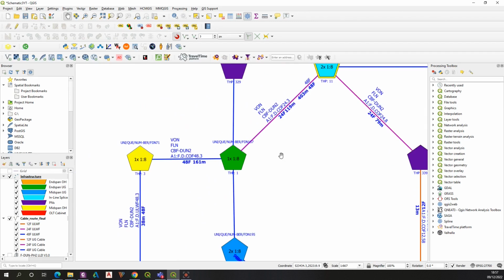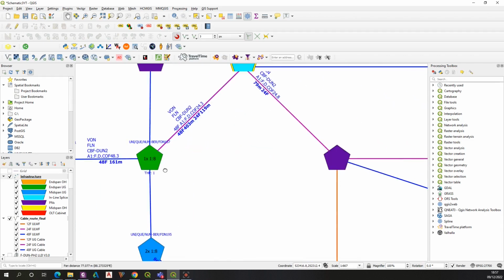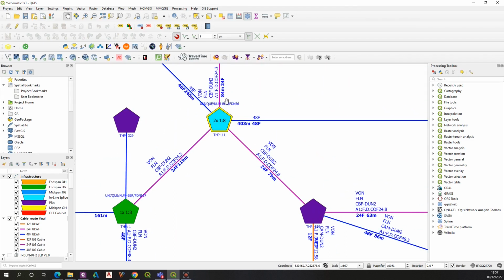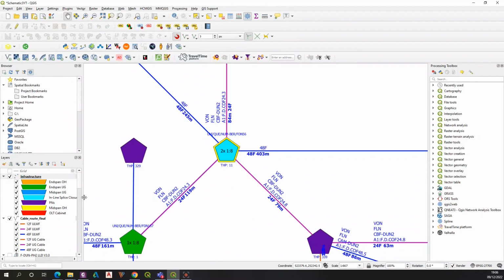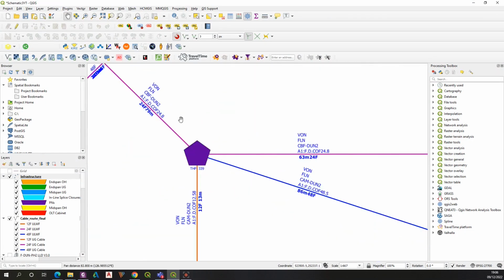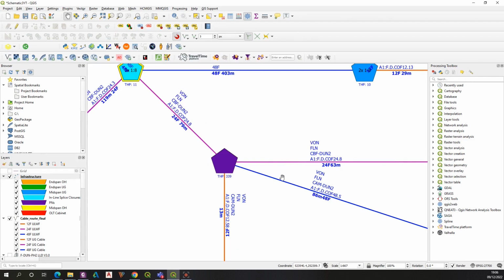And this label position, same as cable routes, impacts the labels defined for nodes, the point layers, which can be seen for example here. We've got effectively 5 cable routes going from this in-splice closure. It's not difficult to find other examples, even adjacent ones, where usually a few, or at least more than 2, cable routes go from the given node, the given point item.